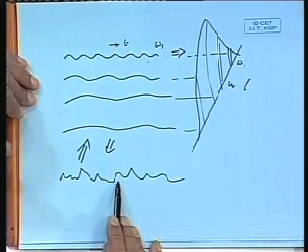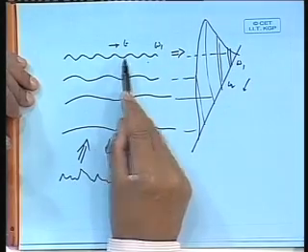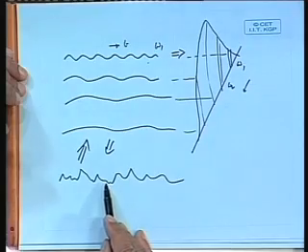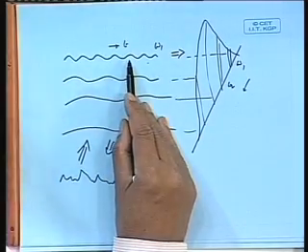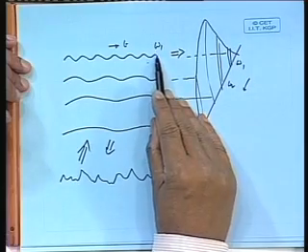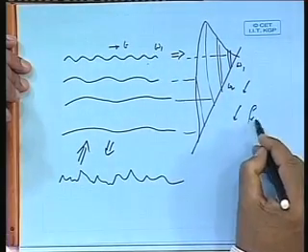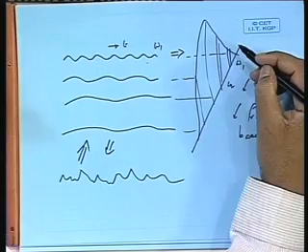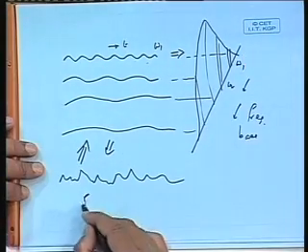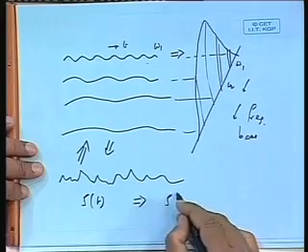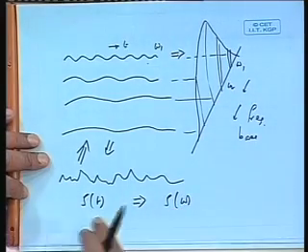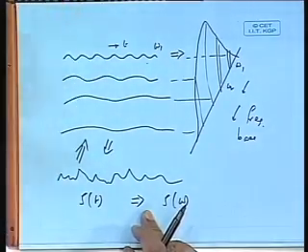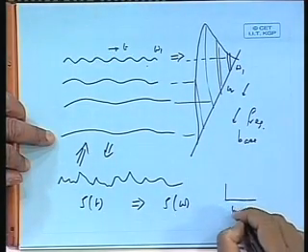See, you have broken it down to various component frequencies, omega 1 and corresponding amplitude 1, omega 2 corresponding amplitude 2, etc. So this can be thought of as composed of these frequencies with the corresponding amplitudes. Now you are plotting this frequency as the base. This is my frequency base, and a quantity proportional to amplitude square. In other words, whatever you had, xi against t, you have transformed into xi against omega. In fact, a signal you had in time domain, against time, you have represented in frequency domain, against frequency, because you are plotting against omega.